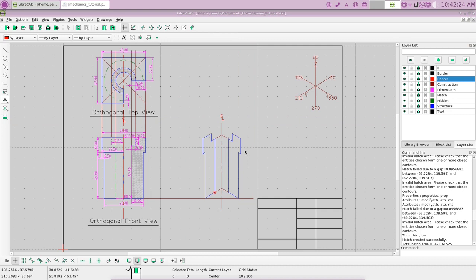Okay, so now we're going to begin with a few more of our lines. Let's go back to the structural layer, and we need to draw a face here and a face here. So let's first start with an angle line at 30 degrees is fine, but we need 22.5 is what we need for length, and we need to snap on end.